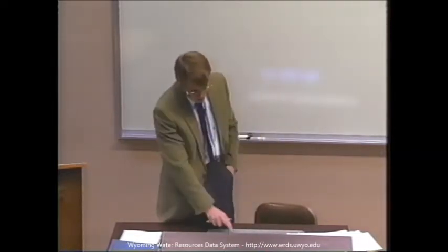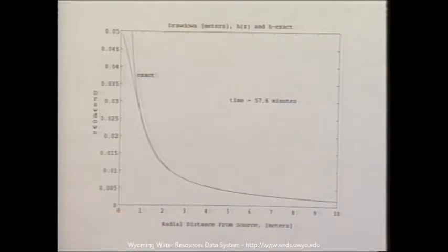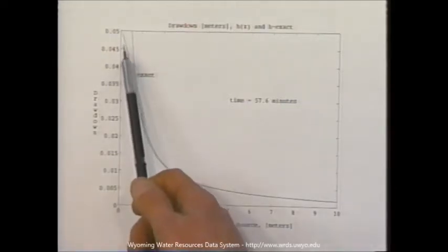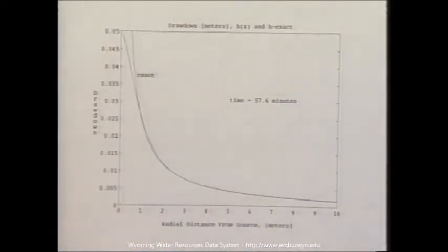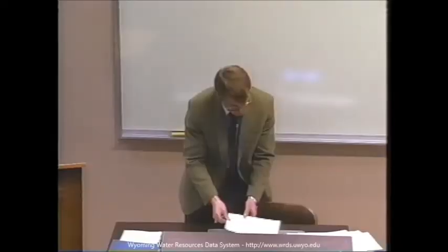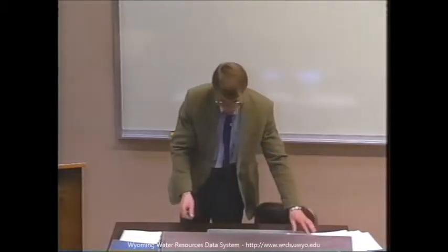This is essentially the same thing, only at a time of 57.6 minutes on down. Once again, I've got a little bit of smearing. The exact solution is shooting up to infinity. And beyond 3 meters radial distance, you've got a fairly accurate model. Now this is with elevation.